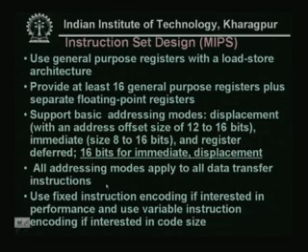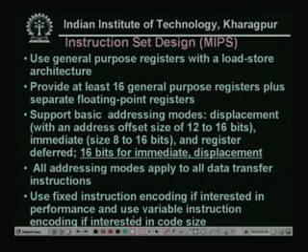Now, how are the instruction sets designed? It uses general purpose registers with a load store architecture. This is the basic principle of RISC architecture: load store. Provide at least 16 general purpose registers plus separate floating point registers. So, it keeps a number of registers: 16 general purpose registers and also some floating point registers.